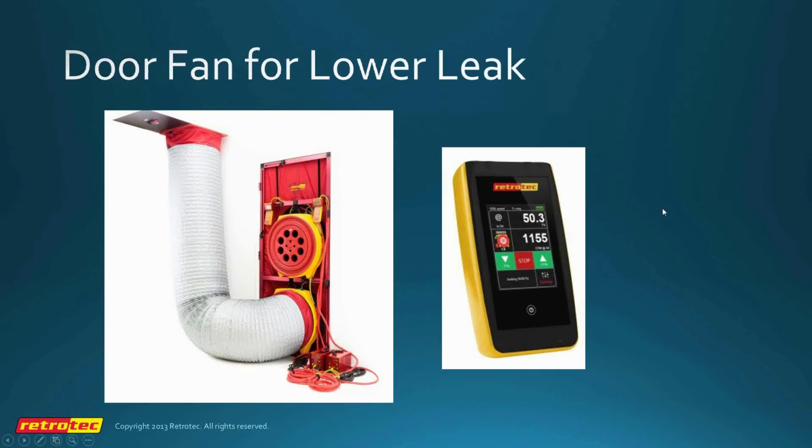So that's one option. The other option is to use the door fan to measure the lower leaks, and here we have this apparatus that we pioneered, and it has 2 fans. This fan is measuring the lower leak, and this fan is doing nothing but pressurizing the above ceiling space so that we don't have any upper leaks in our measurements. So this one's taking care of the upper leaks, which we're not measuring.